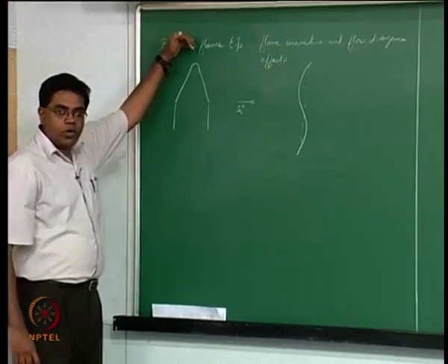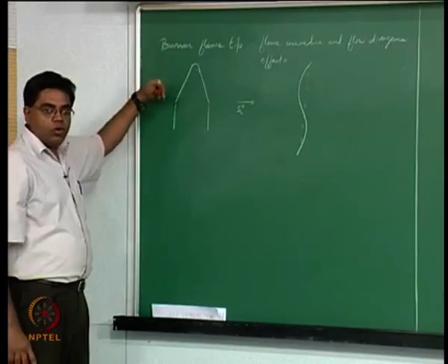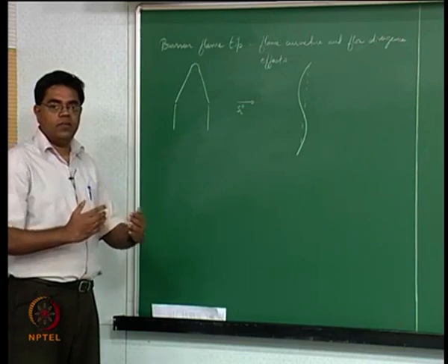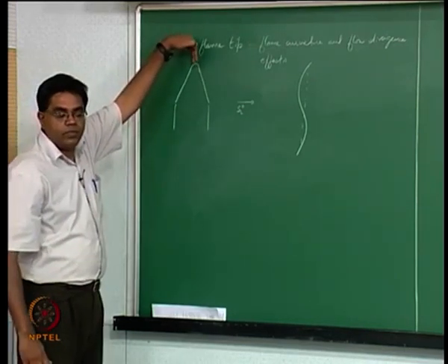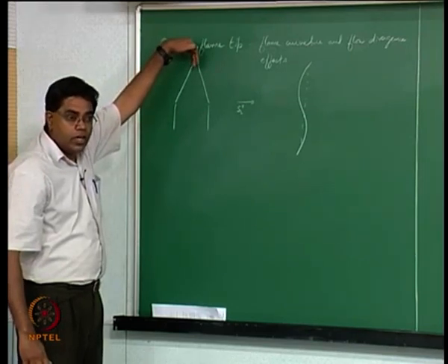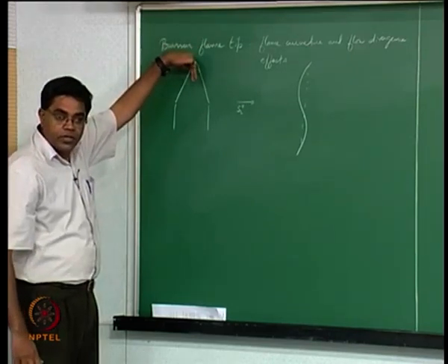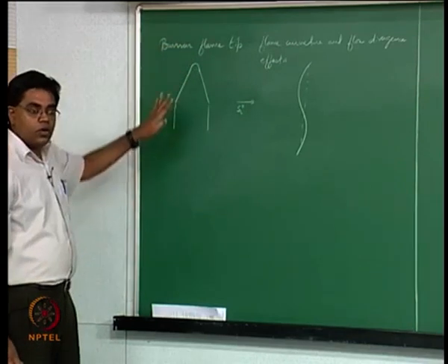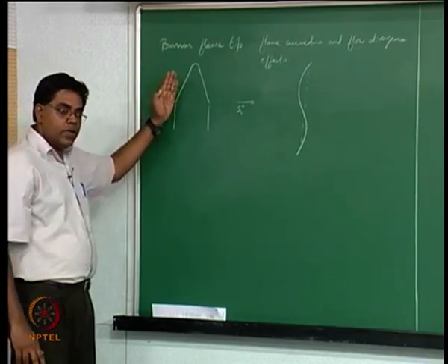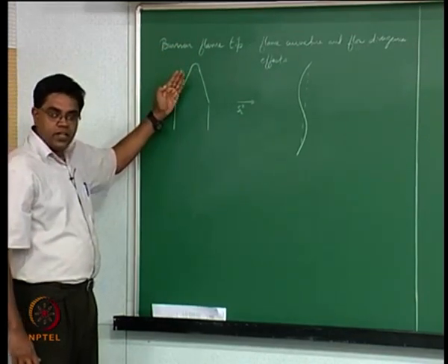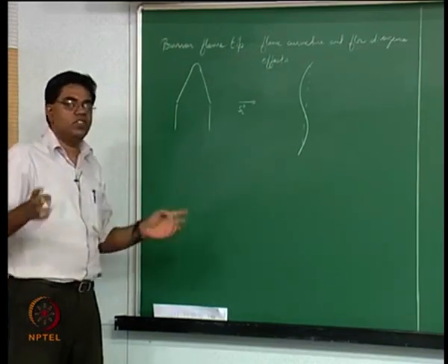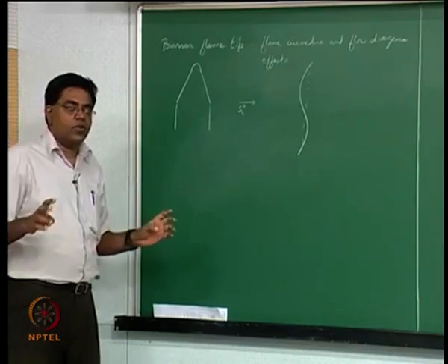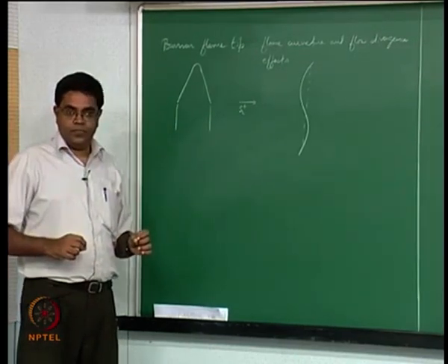But that is true for most of the shoulder of the flame. If you now think about what happens to the tip, no matter what the flame speed flow velocity balance is, the tip also always has to propagate against the flow directly, right. So no matter what the flow speed is and how the flame speed is able to balance that, the tip always has to adjust itself to match the flow speed to the extent it can. So the question is, how does that happen?